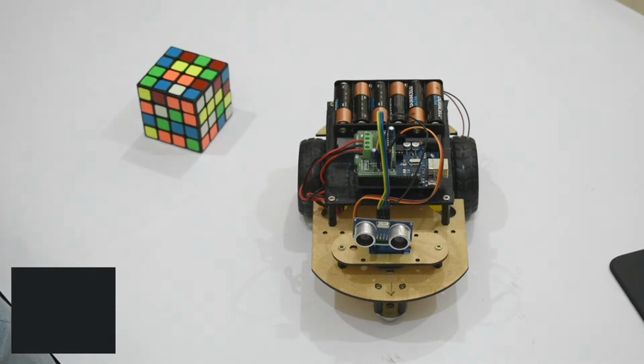I'm saying that because the loop is going to run again and again, and my servo might take some time to go to this 90 degree angle. So after this line runs, wait for 1 second, in which my servo is going to rotate, and after that it starts running the loop function again and again.